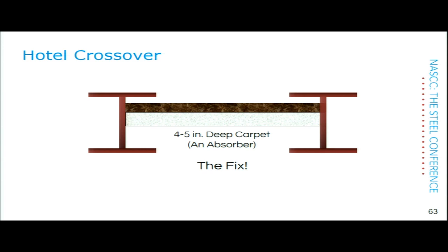So the architect came in with carpet and undermat and padding and just kept piling it on the bridge until it was about 4 or 5 inches thick. He said, this is it. And you had to wade across this bridge to keep it from vibrating. It was an absorber. They opened up the hotel with that fix.